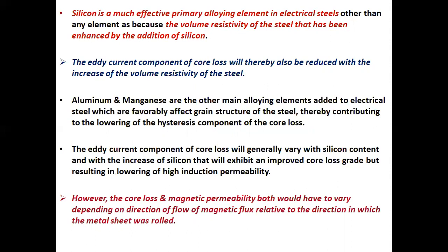The eddy current component of core loss will thereby also be reduced with the increase of the volume resistivity of the steel.